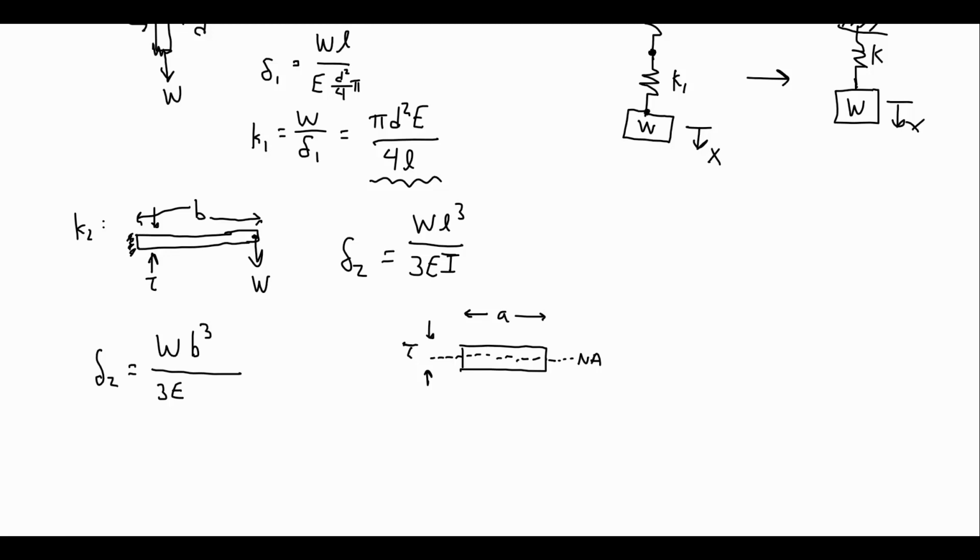So thinking back to strength of materials for this, I'm going to need to use that it's a rectangular cross section, so it's that 1/12 BH cubed generically. In this case specifically, it's 1/12 B, where B is the linear parameter always parallel to the neutral axis we are bending about. So actually that is going to be A in this case.